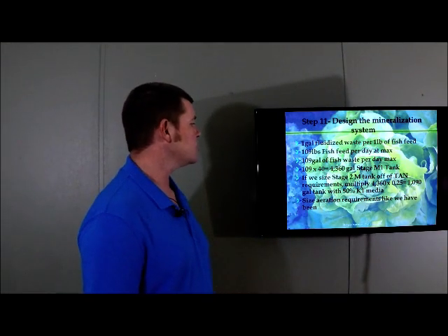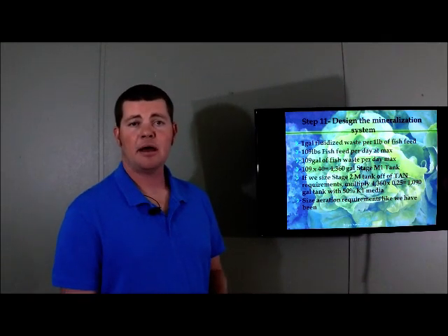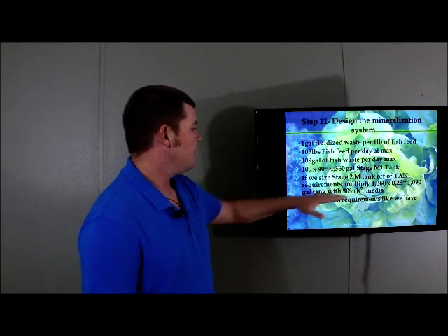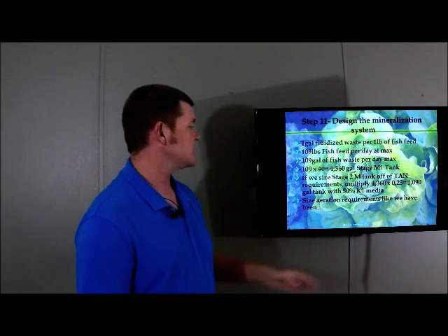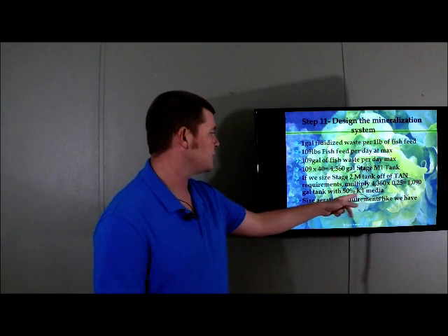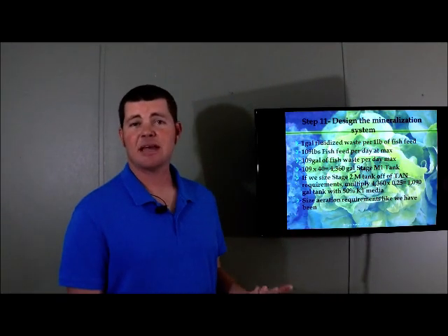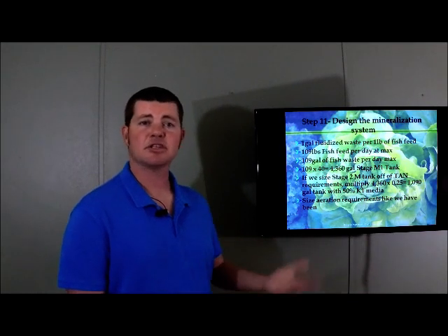And then we size aeration requirements just like we have been. Very easy, 5 times the culture, or the vessel volume, so 5 times the biofilter volume, that 1,090 gallon tank. So 5 times that, and we convert it to CFM. That gives us our air volume.